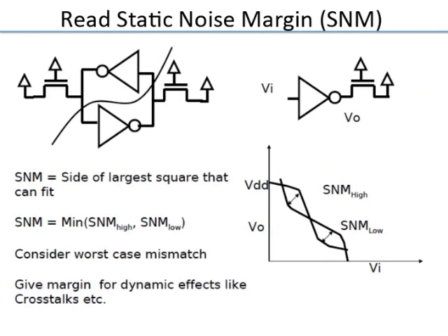There will be a mean threshold voltage and there will be some variation. The foundry will say these are all the random parameters. They will give you the sigma, the standard deviation. Then you run multiple simulations with different values sampled from the distributions for these parameters. So that is a Monte Carlo.